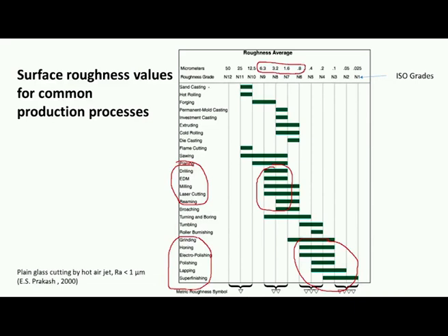Now you can see this is sand cast process. In the case of sand cast surface, the finish will be very rough, like 12.5 to 25 micrometer Ra. So if finer finish is required because of the movement of other sliding surfaces, then we can go for machining operations to produce the required finish.